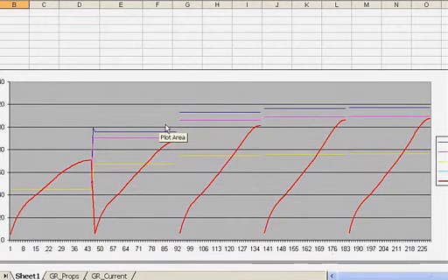I deliberately opened up the air gap to make the copper the dominant loss in this ferrite inductor, which it probably is in a practical ferrite inductor at 10 kilohertz. And so the main thing causing the temperature of the device to rise is the copper loss itself.